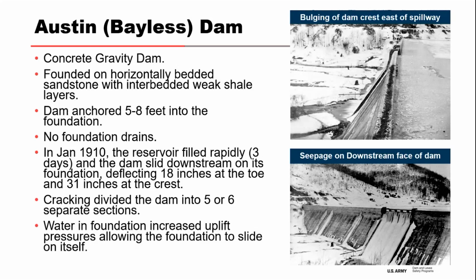So the reservoir was lowered, and the partial failure was attributed in part to the concrete not having had time to reach ultimate tensile strength, and water was able to get under the dam and increase the uplift force on the structure, which reduced that sliding factor of safety and allowed the foundation to slide on itself.